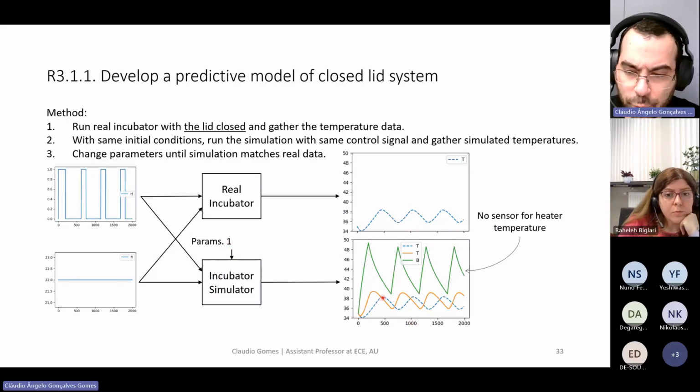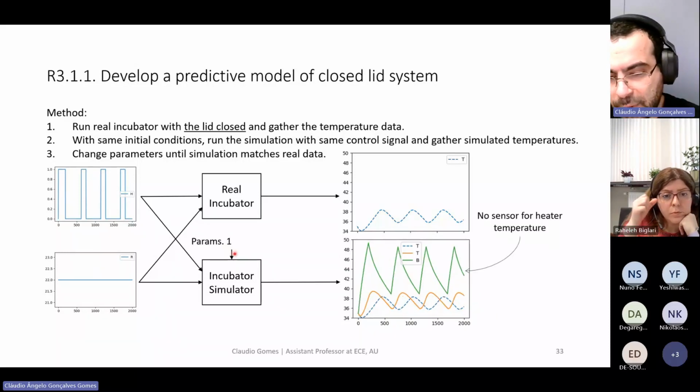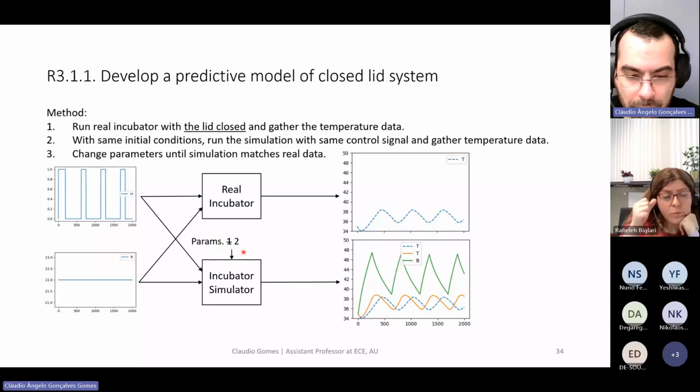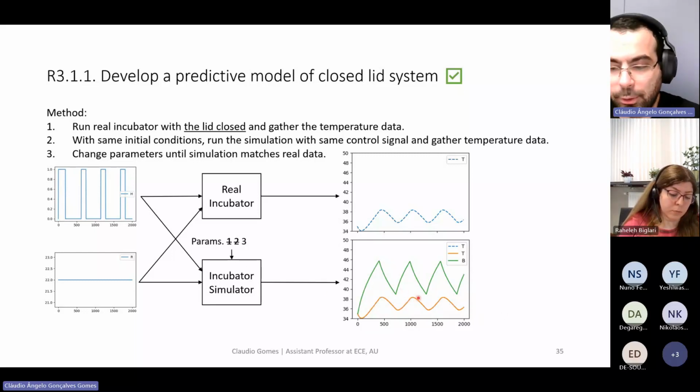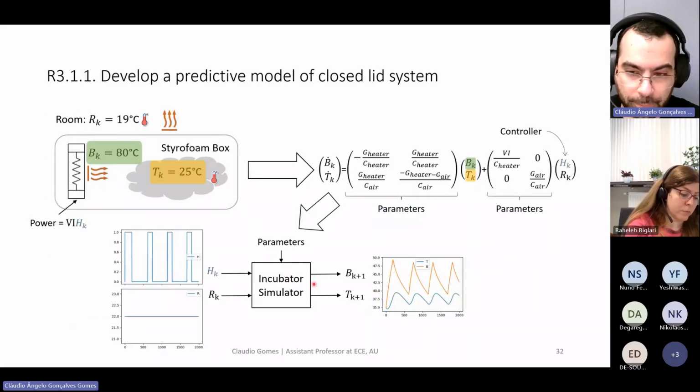And this typically leads to a bad simulation result that doesn't quite match. But then we can use this previous one and adjust the parameters a bit more, and we can keep adjusting until the simulation results for the period of our simulation are in good agreement with the data. And that's how we calibrate the parameters of our model.